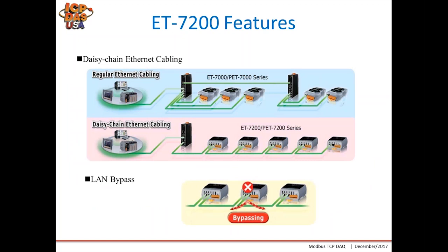This sometimes will help minimize the software or cabling required, because Ethernet can connect a module up to 100 meters away. If you laid a single device with a connection 100 meters, but you had 5 devices, by daisy chaining you can lay one 100-meter cable and then a few short runs to the accompanying modules right next to it.